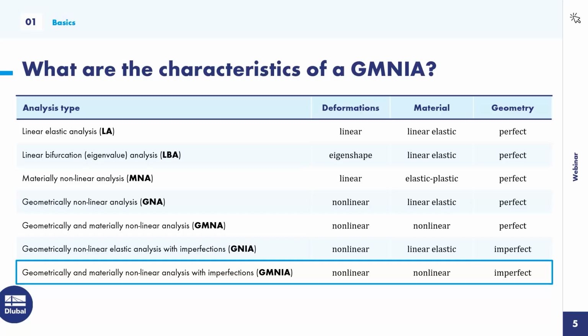To be honest, we could also design a standard plate girder that we tackle in our example today using formulas given in Eurocode 3 part 1.1 and part 1.5. However, if we want to examine special design variants of such standard girder, e.g. the influence of web openings in critical regions, or we want to investigate how the plate girder performs when we use corrugated webs instead of plain ones, or we have discontinuous sections. In these cases, a GMNEA can often be the most economical design method.